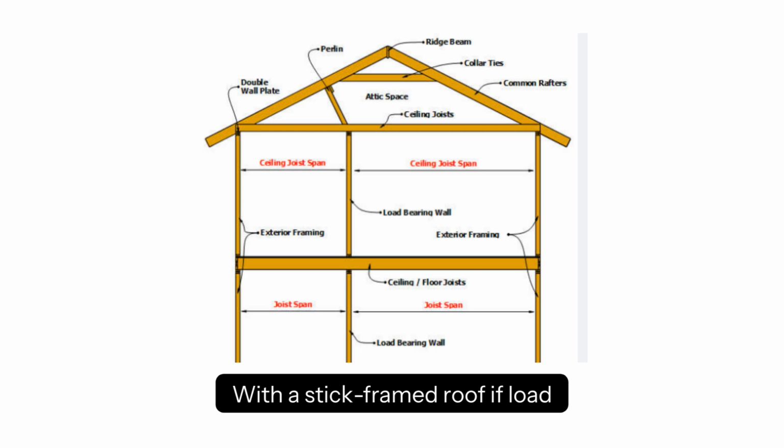With a stick frame roof, if load points are not fully engineered at the time the floor package is designed, it can leave the supplier guessing and either missing loads or over-designing the floor system, costing money. Per the IRC and IBC codes, the person taking on the building design is responsible for specifying the loading.